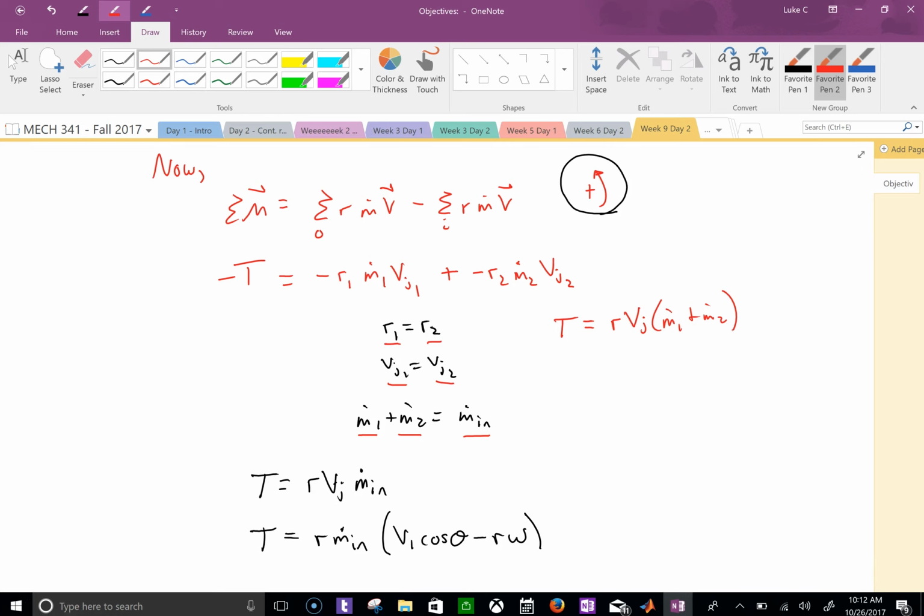This is the amount of water you put in this one. These two are out. This is the one that's coming out. So m dot 1 and m dot 2 are out. But based on conservation of mass, m dot in equals what? M dot out. You have m dot in equals m dot 1 plus m dot 2. So you can combine those two to get m dot in. You could leave them as m dot 1 plus m dot 2. I just simplified it.